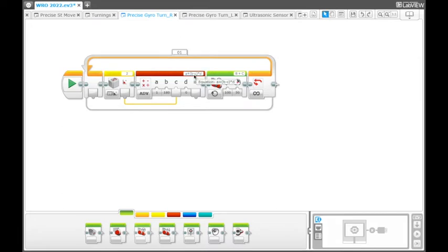That is the reason I am multiplying with D. What this D will do is slow down the robot a little bit. For example, if I multiply this B minus C with some decimal number, for example 0.7, it will decrease the speed of the robot. In this way you will be able to increase or decrease the speed based on the requirement.